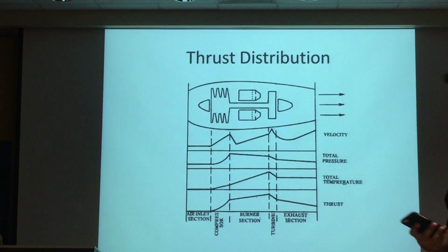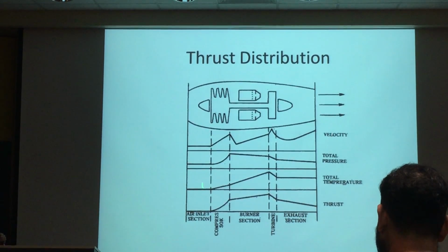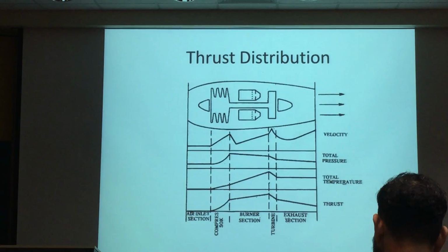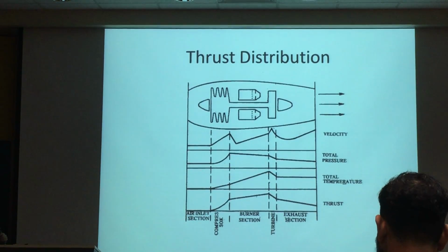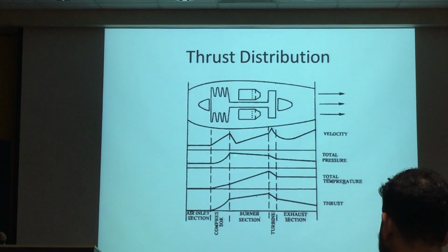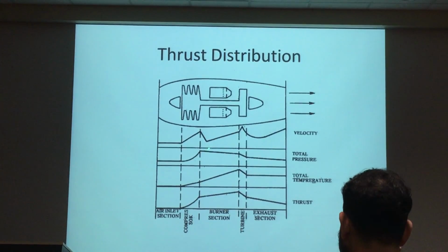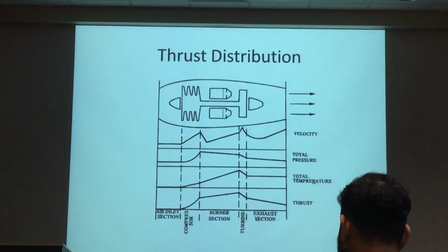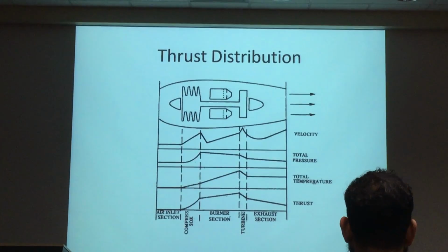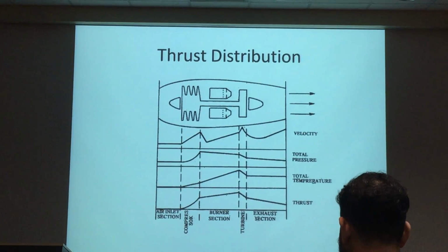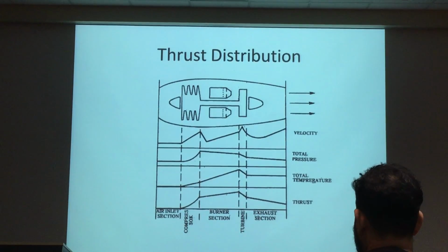Okay, same thing. This diagram here is to show you the diffuser. Remember the formula for the Brayton cycle is constant pressure when the gas expands. So from the diffuser all the way to the nozzle guide vane, it is supposed to be a constant pressure. But because of losses there, the pressure suddenly dips down. So the higher pressure is usually exactly at the inlet to the combustion chamber, or the diffuser chamber. So your PT3, correct? Your burner pressure is measured at this point, the diffuser pressure, or PS3, we call it burner pressure.